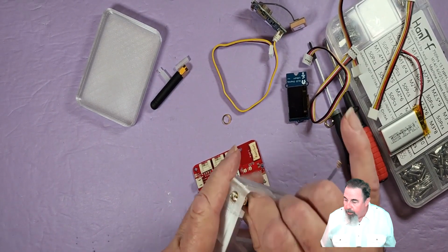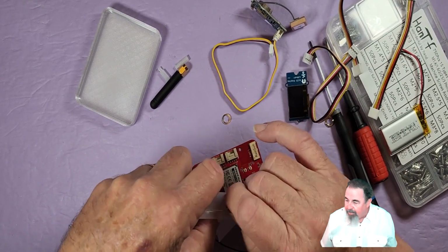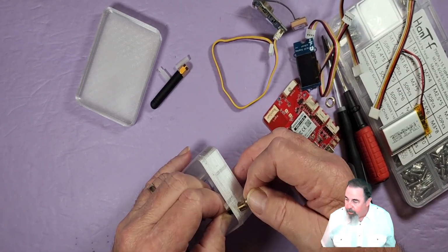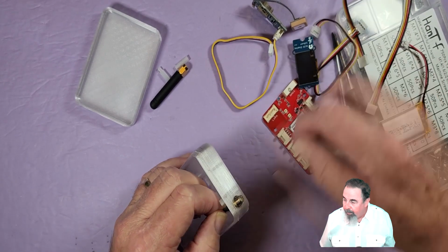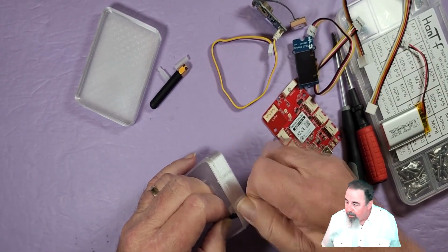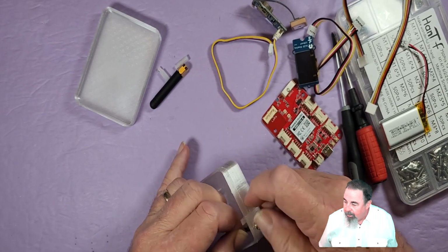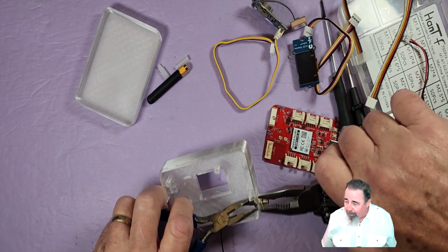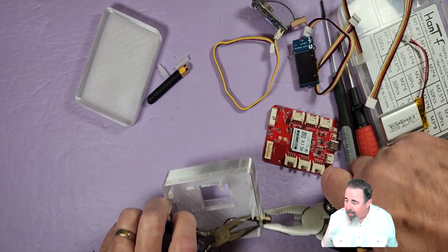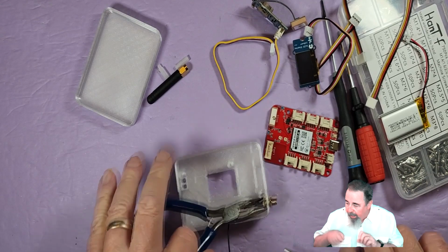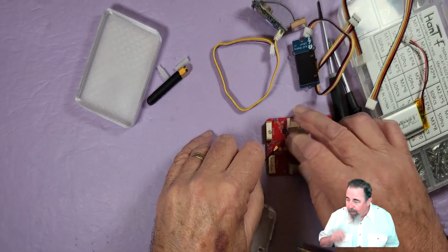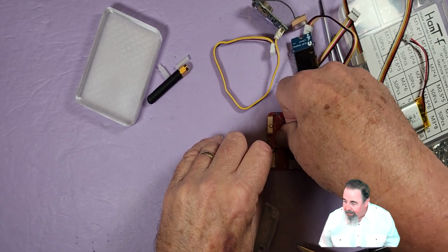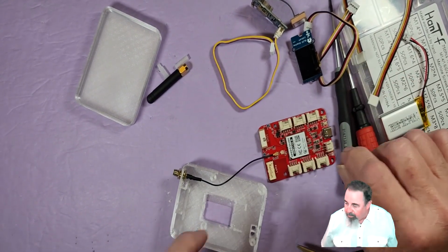Okay, so first thing I'm going to do is assemble this antenna. I have a Heltec 1 dBi antenna from one of my Heltec V3s. We'll just go ahead and use that. That's not included with the WIO 1110. I was debating putting the 175mm antenna on here, but I just wanted to get the little stubby antenna for the moment. I like getting the pliers and really making sure that's tight, because I hate when you want to change out the antenna, you wind up loosening the mount itself and it spins freely inside the case. Then you have to take the case apart, and so on and so on.